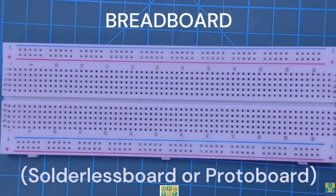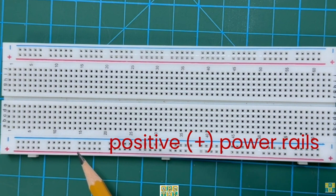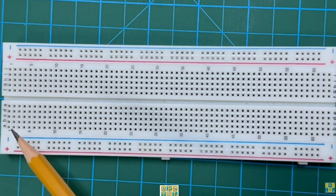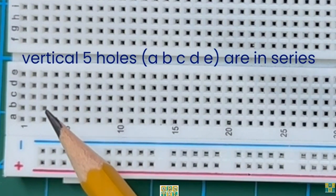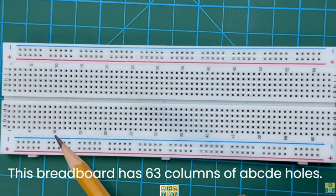Now, for the breadboard, this is also called solderless board or proto board. We need this to connect our circuit. These are the positive points, and these are the negative points, and they are all connected together. Now, the A, B, C, D, E vertical, these are called the terminal strips, and it's like series connection, okay? A, B, C, D, E, vertically, you can connect 5 holes together. And we have from 1 to 63 on this board with A, B, C, D, E connectors.